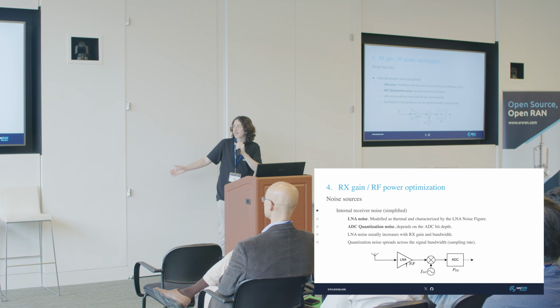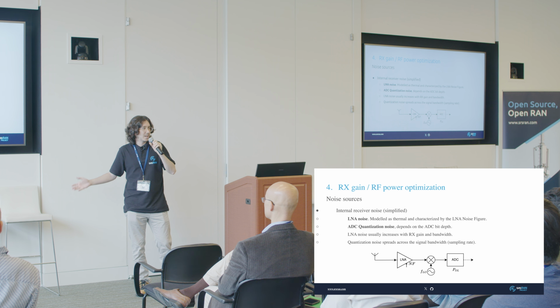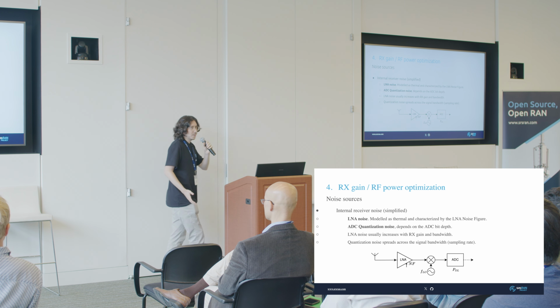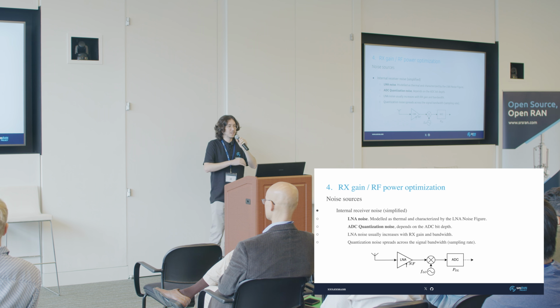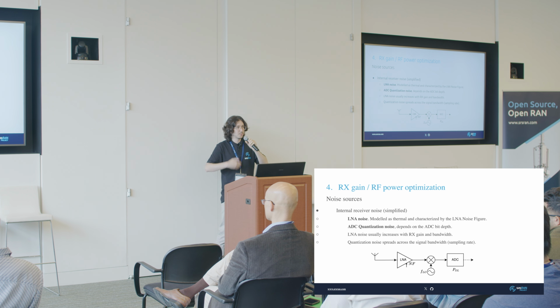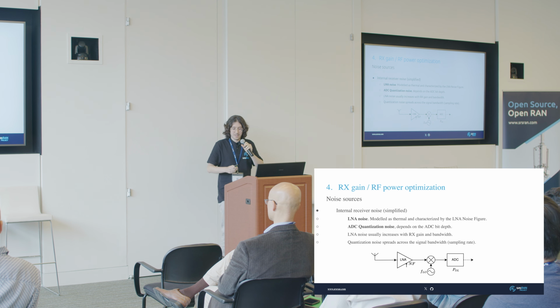There is another point: the noise that is introduced by an LNA, as well as the RF noise, usually increases with bandwidth because it's a specific spectral density, which as I have more bandwidth, all the contributions start adding up. But the quantization noise actually doesn't work like that. It's because actually it's not a noise, it's an error, and it's distributed across the entire bandwidth, but I'm not going to get into that in more detail.